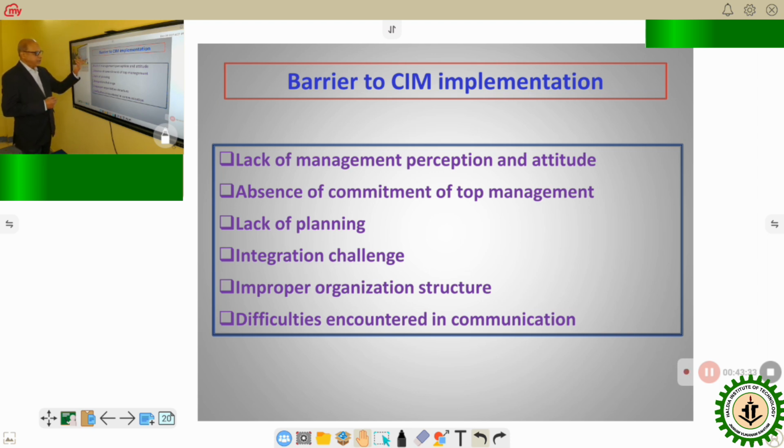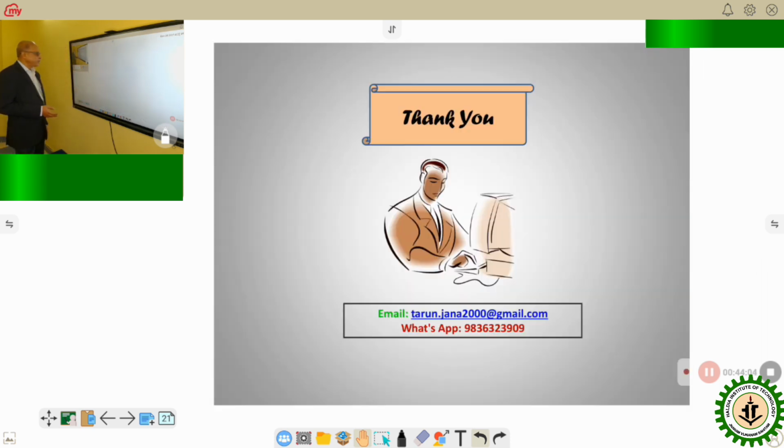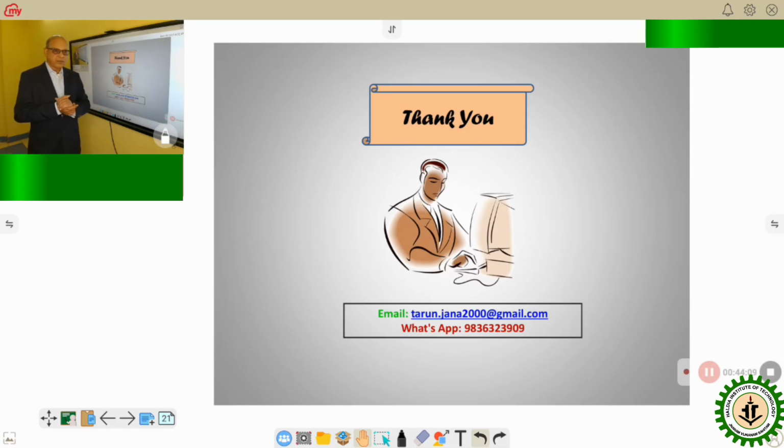Another deficiency of CIM is the hierarchical structure. It is a rigid orthodoxy that inhibits some amount of flexibility. So afterwards, as the challenges increased, there was a need to migrate from hierarchical to heterarchical architecture. Eventually, the holonic manufacturing system and agent-based systems, these hybrid or heterarchical architectures were much more flexible, agile, and responsive. So that is perhaps all about computer integrated manufacturing as far as your CIM content and the syllabus is concerned. That is the highest level, that is the enterprise level